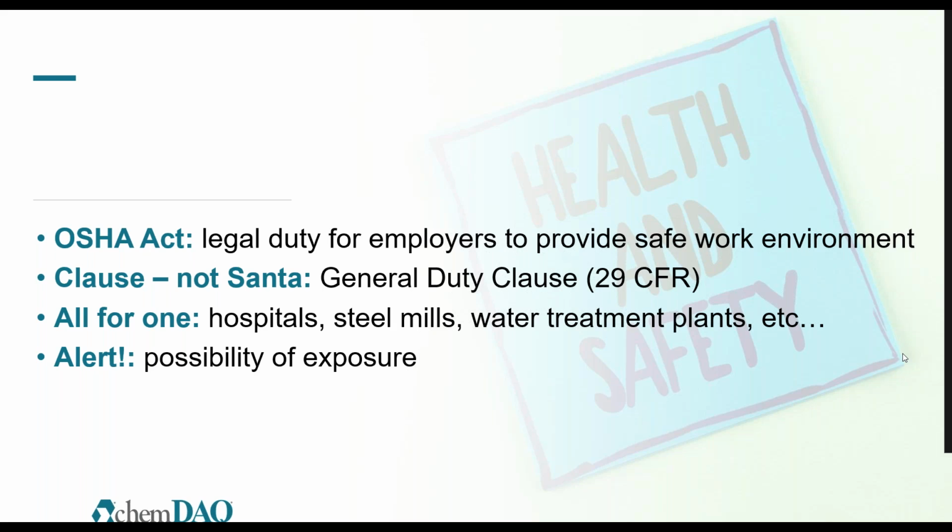So the other thing I was going to add, sort of reinforcing what you just said: in addition to the OSHA laws, a lot of states also have their own permissible exposure limits. So, for example, with hydrogen peroxide, there's the OSHA permissible exposure limit of 1 ppm over 8 hours. But a couple of states like Washington and Hawaii have short-term exposure limits of 3 ppm. And so, in those states, the employer has to follow both the state and the federal regulations.